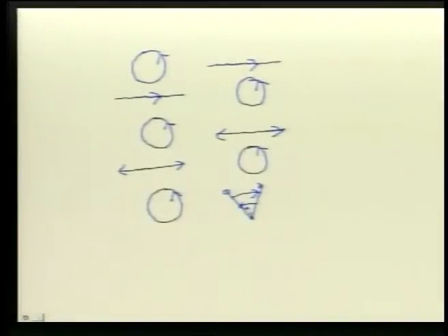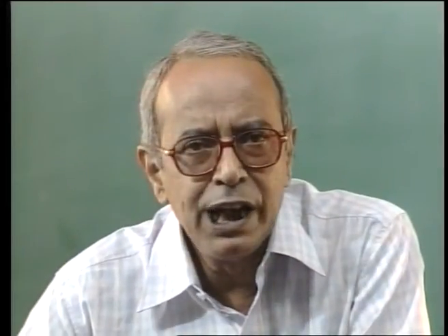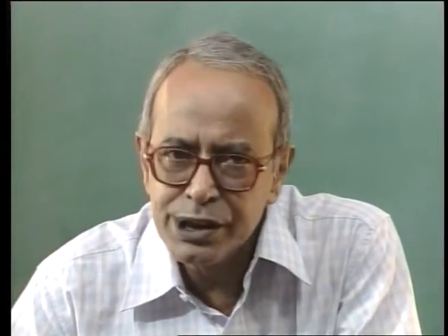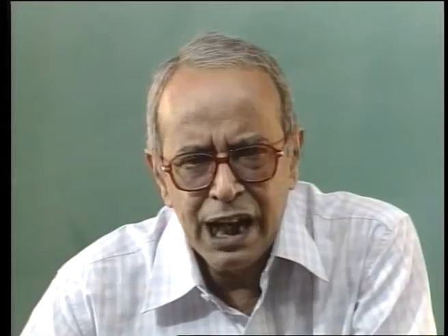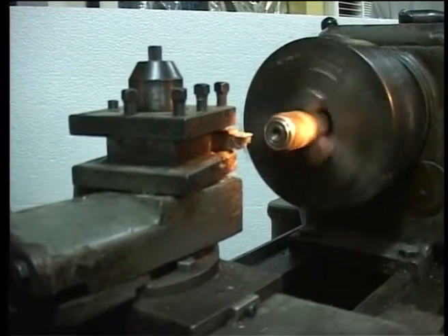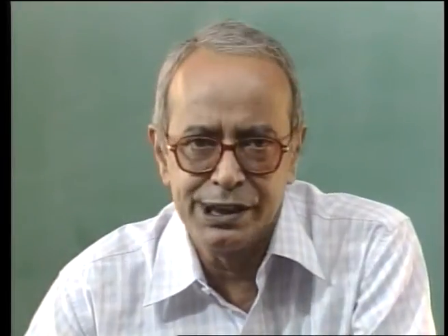At this stage, let us talk of a real life machine, that is the most common machine tool, which we call a lathe. Here the input motion is available at the shaft of the driving motor, which is the input motor, normally located at bottom left end of the machine. This motion has to be transferred to two different locations, that is to the headstock to provide motion to the job and also to the tool post, that is to provide motion to the cutting tool. Let us see during these two transfer processes what kind of transformation is taking place.